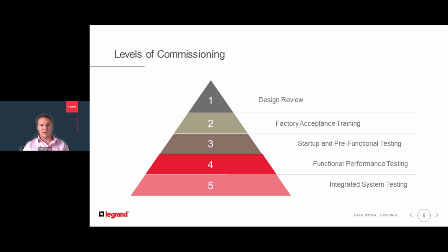My team in particular has been going around a lot of times now and getting a lot of requests on how do we comply with NFPA 70B standards now, right? And a lot of ways to do that is, okay, let's add some IR windows to your feed so that we can check on your lugs. Let's go through and do a preventative maintenance plan, and we'll verify all that. Let's do it on a 1 year or 2 year basis. Let's be fair with it and make sure that we're not overdoing it, but not underdoing it as well. And make sure that we keep that customer in that data center or industrial facility up and running.